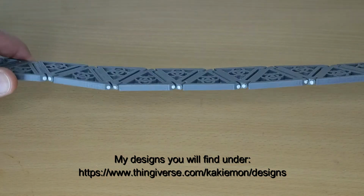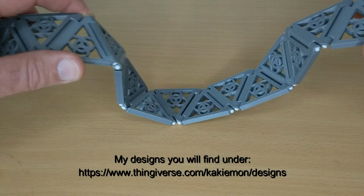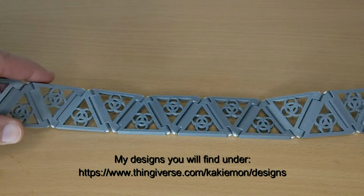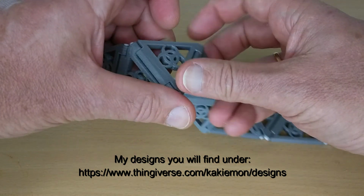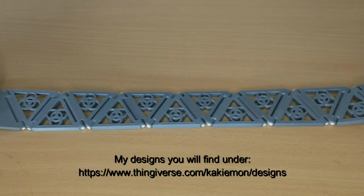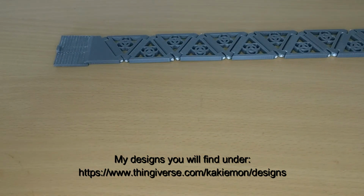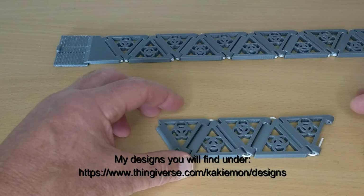On the belt in the video I used 1.75mm PETG filament I melted at the ends using a flat soldering iron tip, so they could not move out anymore. But the same way a stable, soft cable wire you route in a zigzag way does the same job.